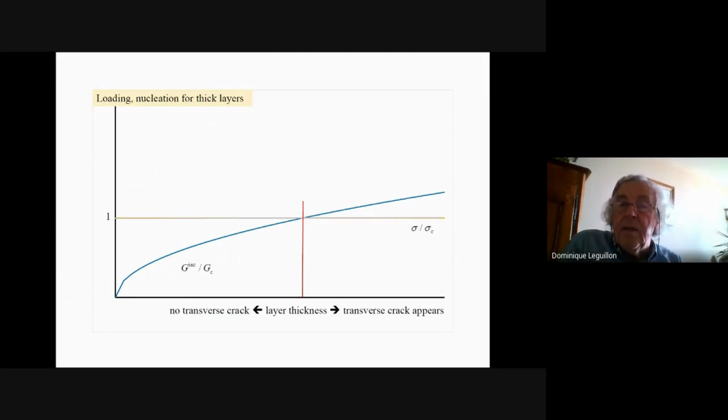And this is the right part of the curve of Parvizi, you know, where it is governed by the stress here. Because as soon as we reach the stress condition, failure occurs. But if the inner layer is thinner, I mean, it is in this region, you see that, for instance, for this thickness of the inner layer, the energy condition is not fulfilled.